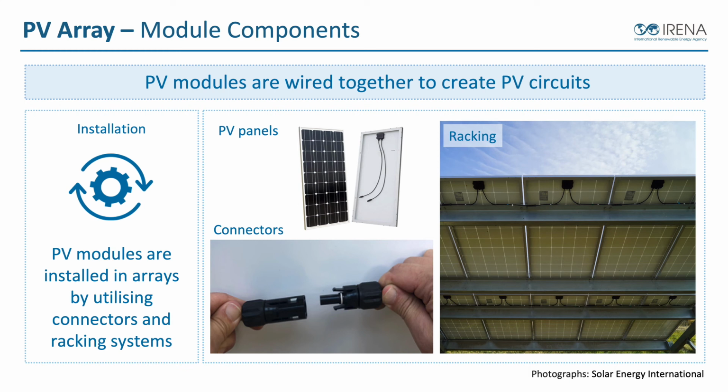The connectors that we see on solar modules are designed to be touch safe and waterproof. And so if they're put together correctly, then we can have a good electrical connection that's allowed to live outdoors for the majority of its life. Now, the other parts of the module itself: most of the modules have a frame, some sort of aluminum frame around the sides, and we use that for mounting. So we take the aluminum frame and we bolt it to a mounting or racking structure.